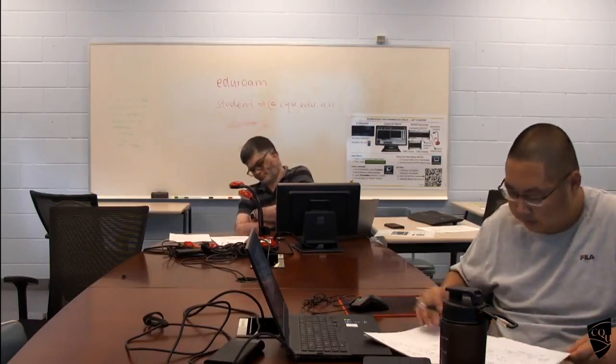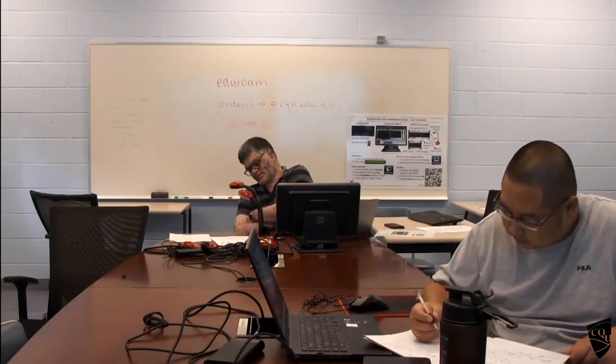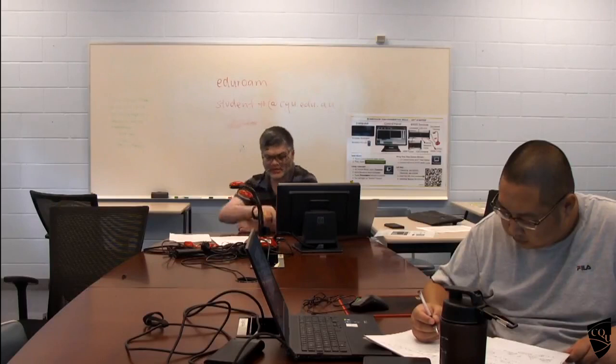So this is B. So this is cracked section, Y bar cracked. Okay. I need to find out the Y bar using the same way as earlier. But I had two different materials, so I am going to replace everything with the concrete.